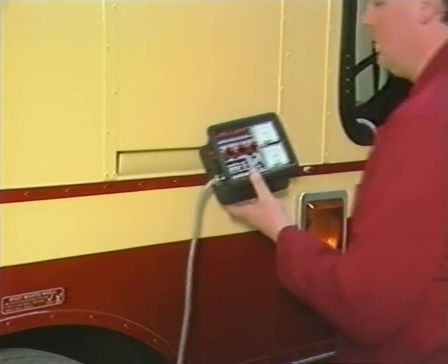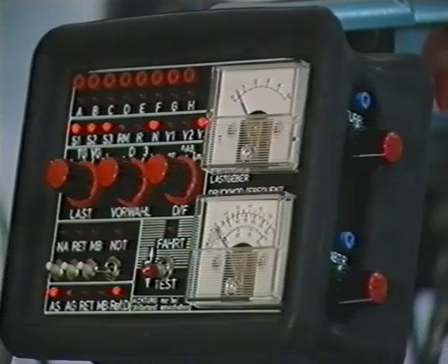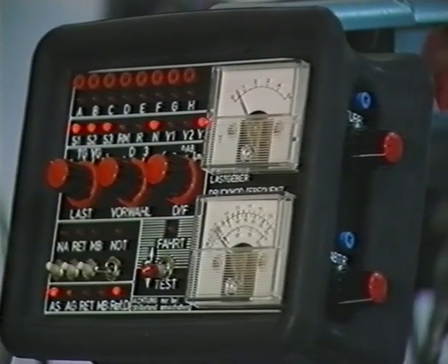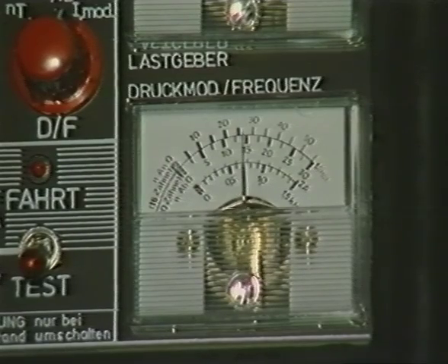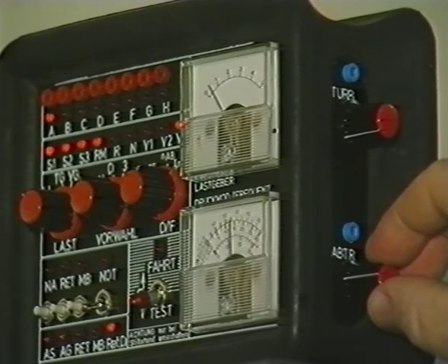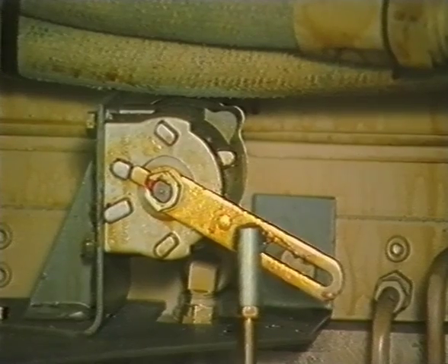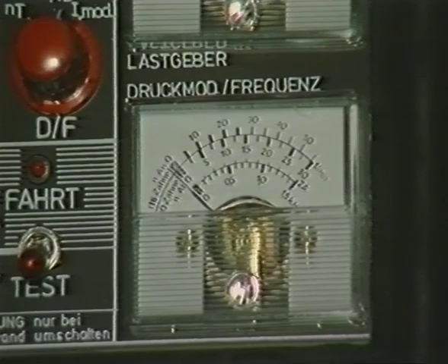If test equipment is available, install as previously described and set the selector switch to MOD. Switch on the ignition and select D. If the system is correct, a reading of 1 amp on the lower meter should be visible for approximately 1.5 seconds. If the output speed control is increased, this reading should occur at each gear change. If the throttle is moved down fully during this period, the reading will reduce to approximately ½ amp.